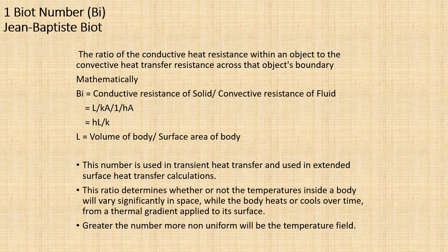This is very important, and in many tests, entry-level or job-level tests for chemical engineers, we are asked about different dimensionless numbers, and Biot number is one of the important dimensionless numbers for chemical engineers especially. Also, it's very important for other fields of engineering. So greater the Biot number, there will be more non-uniformity in the temperature, while if we have a small Biot number, then obviously we shall have a uniform temperature field.